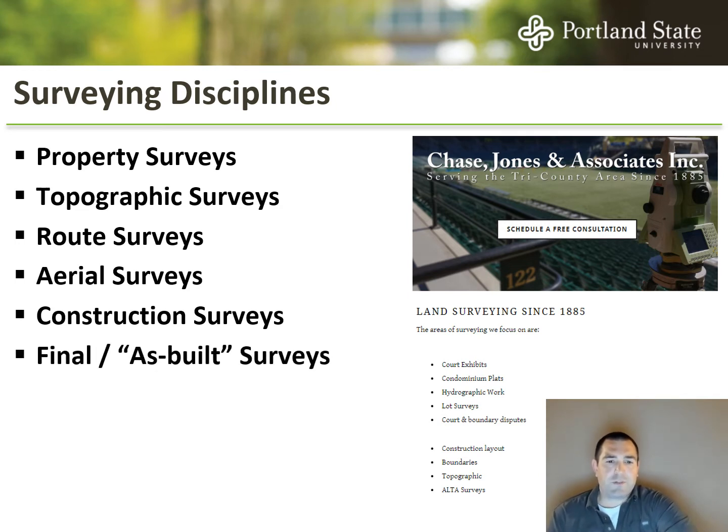Final as-built surveys. So this is kind of like the preliminary survey, but instead of going out and measuring existing conditions so that we can put a new civil project on it that we've designed, this would be after construction is complete. Oftentimes we'll hire a surveyor to go out with the plan set and then mark up the plan set to show what the actual dimensions are. So let's say we design a bridge to be 50.25 feet wide. We give those plans to the client, it goes out to bid, the contractor builds the bridge, and we want to know: is it actually 50.25 feet wide?